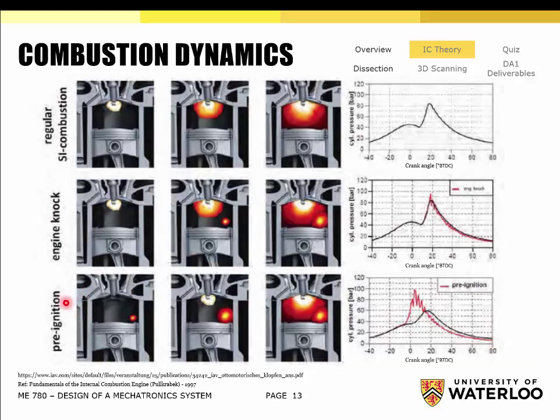So that's how a diesel engine actually operates. It doesn't use a spark plug at all. It just operates on the fact that as you compress the mixture, you're increasing the temperature and pressure to such a point, with such a high compression ratio, that the mixture just spontaneously combusts. So it initially just ignites on its own. And then if you actually ignite the mixture after that, you're going to cause, once again, a competing flame front and a competing combustion event that can cause this really erratic behavior within the cylinder, and this really breaks components. So that's something we want to avoid as well.